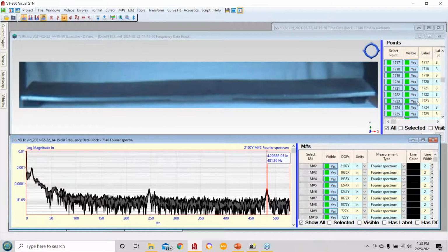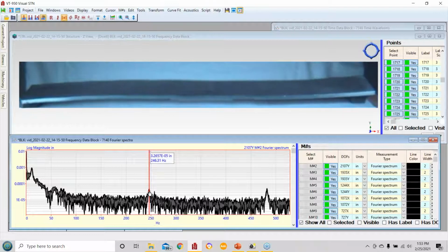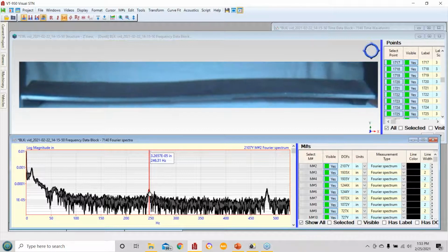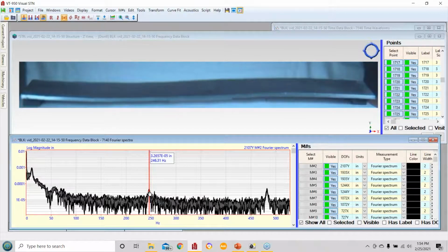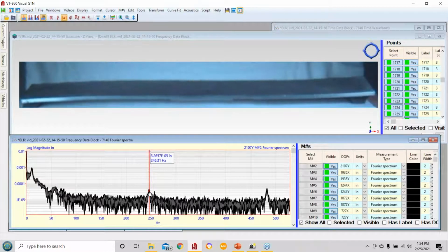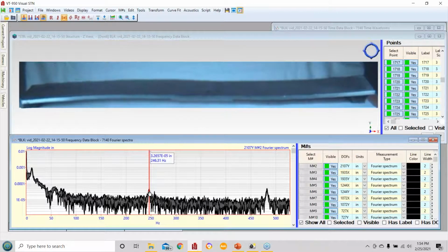Okay, here's the $1 million question. Would you recommend it over traditional ODS, of course, if the frequencies of interest are in range of both methods? One doesn't replace the other. Video has its place for large structures, inaccessible things, hot things, live steam, all the bad things you can think of. The video is hands off, and you can see things that you would never be able to see, and you can't go and put the transducers in.